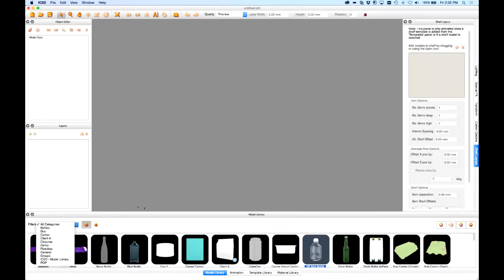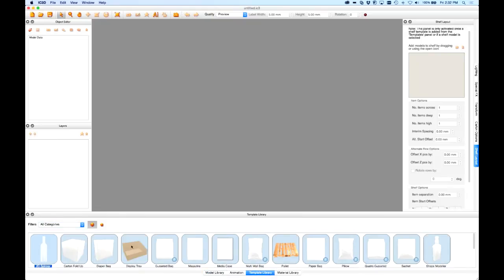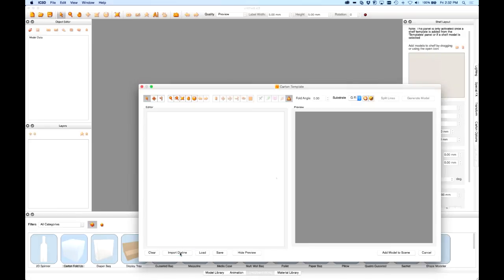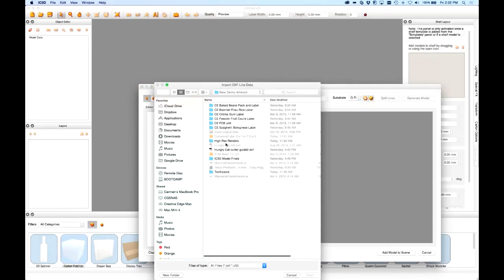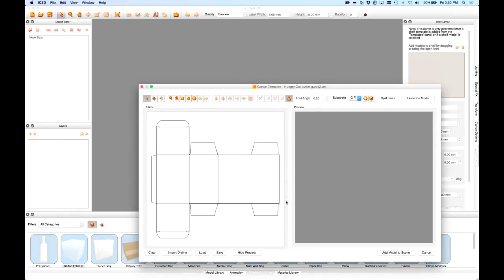Sure. In that case, I'll go back into the carton template that I used earlier, and work with the one that we did. If I bring in that die line from the earlier example, and if my die line had a cut window, I could automatically use that. In this case, I don't have one directly, so I'm just going to select my folds right now, and then draw a cut box within here to show that come out.